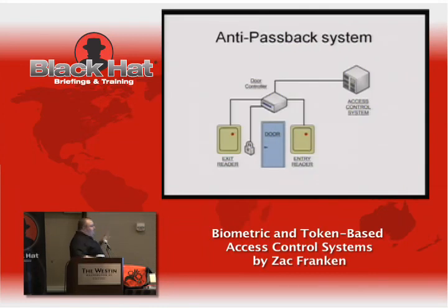Now we have a slightly more advanced system here. This has a local door controller, and it talks to the access control system normally by modem or RS485, and the access control system pushes a set of credentials to the door, and the door then locally verifies those credentials. And periodically the access control system will poll the door controller and pull off the logs as to who went through the door. And this could be real time also.